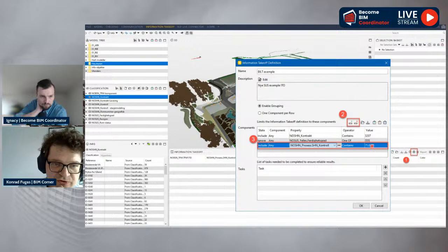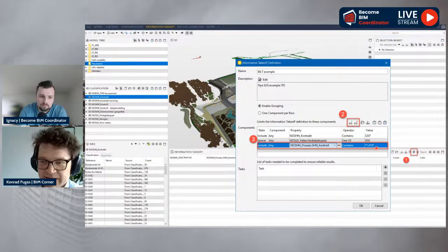You can use, as I used here, a wildcard, the asterisk. It widens the choice. So here it gives me all the objects for the first floor in building 71. And if I had written a number here, it would give me only one control area on that floor. So the asterisk is a wildcard in Solibri which says any, and we can put any kind of symbol instead of this asterisk. Exactly, and how many we want. If you want to use only one symbol, you use a question mark. Okay.